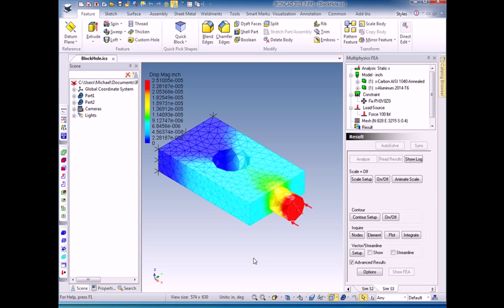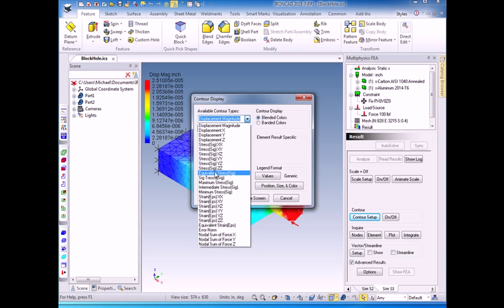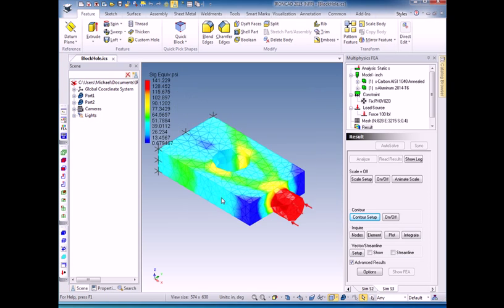the tree up there. So this is the model that we've made where we have a force of 100 pounds applied to an aluminum cylinder here connected to a steel cylinder with a hole in it, and this edge is fixed. The result things that we've looked at so far are the contouring. We've looked at both displacement magnitude contouring, and we've looked at the equivalent stress contouring.